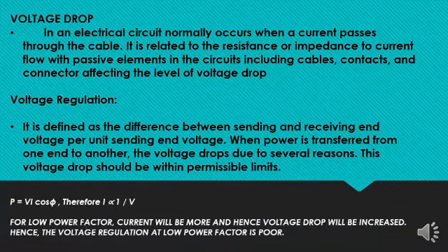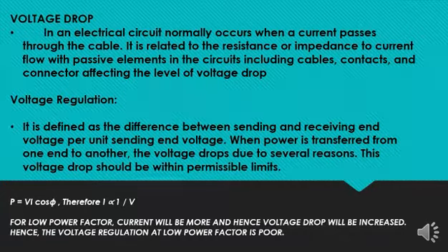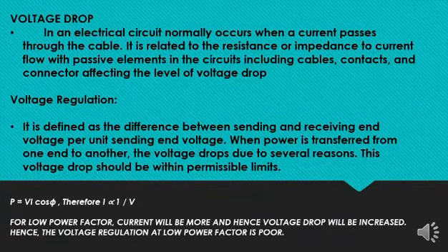To summarize it all, low power factor means higher current, higher voltage drop, and the resulting voltage regulation of low power factor is poor. The most accepted power factor should be higher or nearer to unity, as I mentioned a while ago.